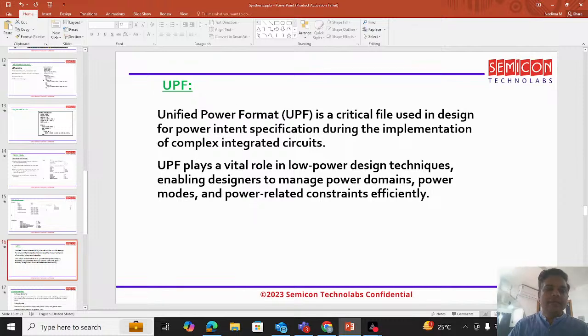As I mentioned before, we have several other techniques to save power. For example, clock gating to save the switching power in the dynamic power. Similarly self-gating, here also we can save the switching power in the dynamic power. Thereby the total power will be saved. We have dynamic voltage frequency scaling. We can scale down the supply voltage, we can scale down the frequency, based on the design requirement. There again we are saving the total power.